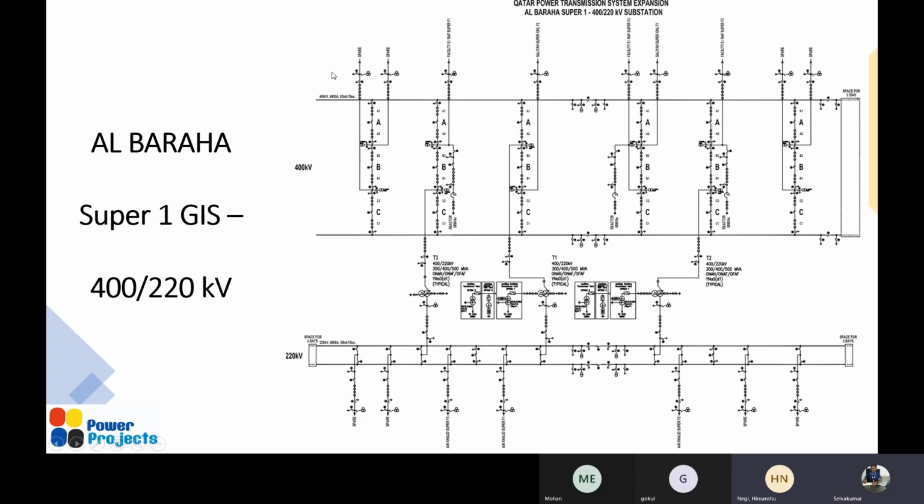So with respect to a transmission line or a cable, with respect to only the fault, we have seen three: terminal fault, short line fault, remote end fault. And for cables, if it's a long transmission line, you have to check the cable energization because the cable injects a huge capacitive current. Probably if you are opening the breaker immediately after closing the breaker, you need to check that. Similarly for a transformer, you need to check transformer energization, transformer de-energization, reactor energization, reactor de-energization.